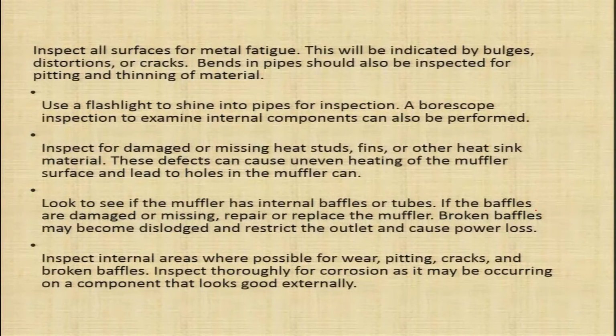Bends in pipes should also be inspected for pitting and thinning of material. So, all the pipe bends should be very minutely inspected for pitting or thinning of the material.